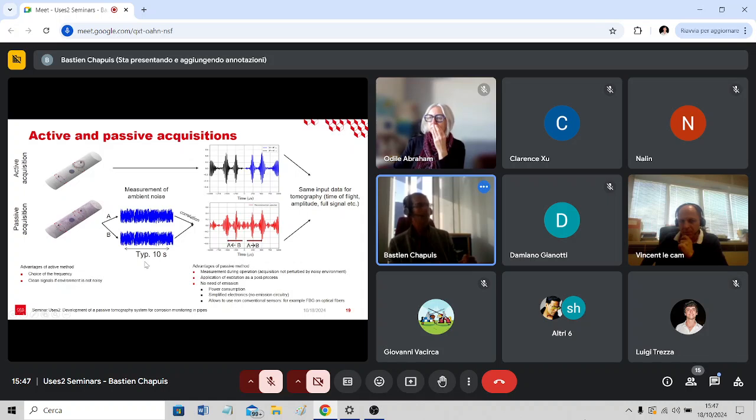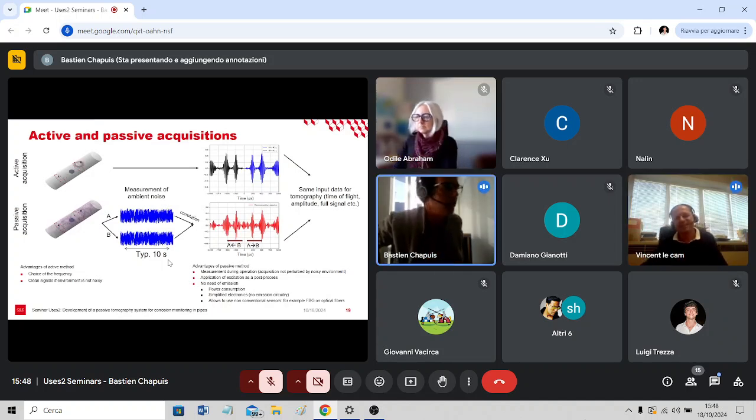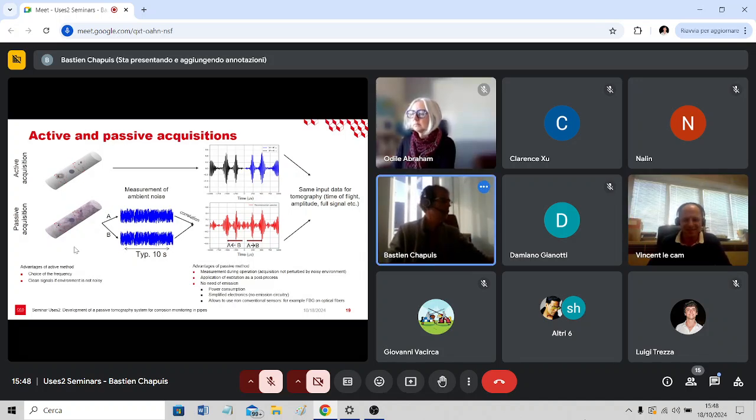And in that case, performing intercorrelation on 2-minute signals captured at 2 megahertz, you have some limitations for embedded processing. We can do that on our laptop, but not on Pegas. On Pegas, a 10 second correlation, I think it doesn't work. So it's more operational limits. It depends more on the application we select, active or passive.